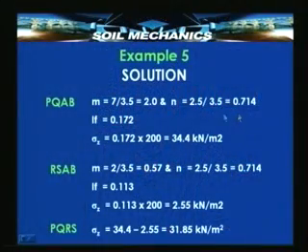Here therefore, there is no problem in determining influence coefficient for any value of m and any value of n lying between 0 and infinity. So, we use that chart. For m and n we get equal to 2 and 0.714, we get influence factor as 0.172. The corresponding stress will now be this influence coefficient multiplied by the load equal to 34.4 kilonewtons per meter square.